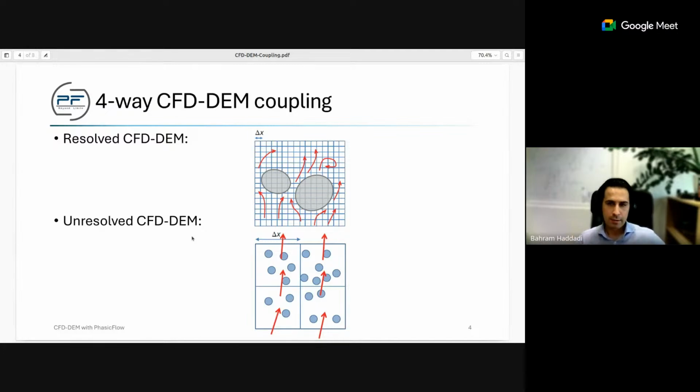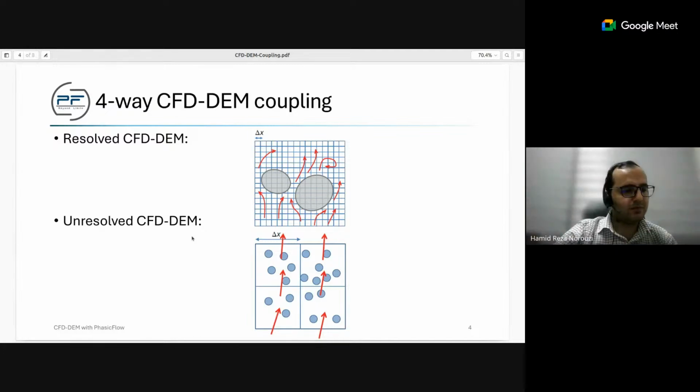Hamid, okay, thank you very much for your explanation. Yeah, that's right. Let me just add one point to the unresolved CFD-DEM. When we are dealing with this system, we need to calculate new variables that represent the dispersed phase.